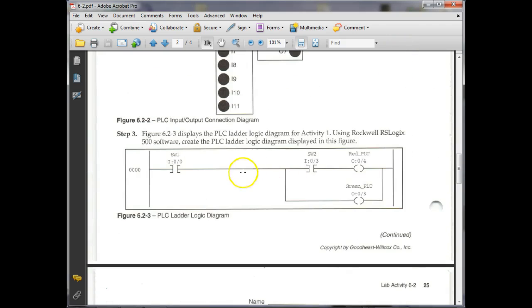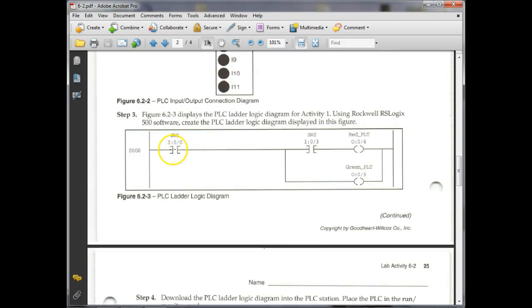Well, they give you the ladder logic diagram, but notice here they're giving addresses 0. But if you're on one of the 504s, and I don't think anybody has to be on one of the 504s, I think we have enough down there so we can either be on the 1100s or the 1000s. Then these are addresses. If you are on one of the 504s, then your inputs are going to be module what? 1, and your outputs are going to be module 2, right? Understand it? We have people go in and see this, and they'll program it just like that, and download it, and then they have problems. It'll pass syntax because it's written right.